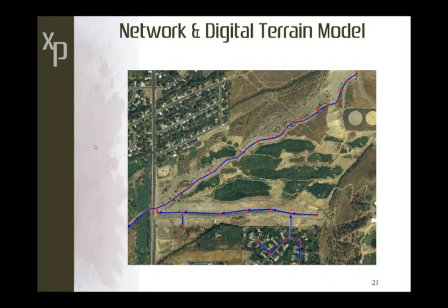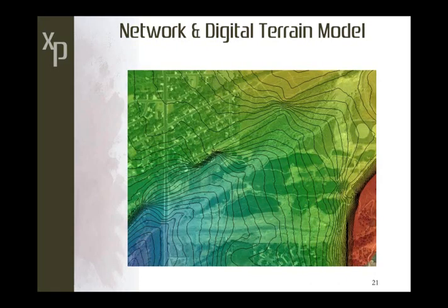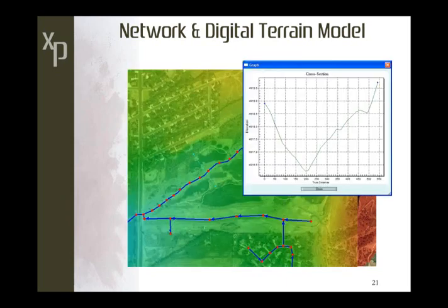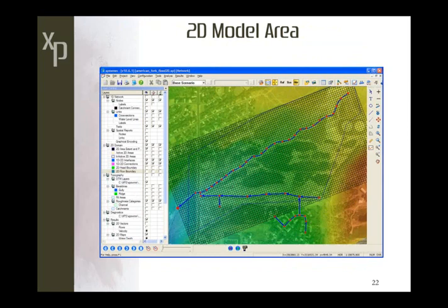So if we get into an example of how you can set up a 1D 2D integrated network, first we begin with our example here. We have a 1D open channel basic network. The main reach you see is our open channel, and the lower portion of our 1D network is a closed conduit urban network. So if we apply a TIN to this, as you can see here, we draped this section to show that we do have that clearly defined flow area for our 1D model to assess. Once you have a TIN and this existing 1D model, you can set up your 2D grid. Essentially, you would drape your floodplain area with the grid.